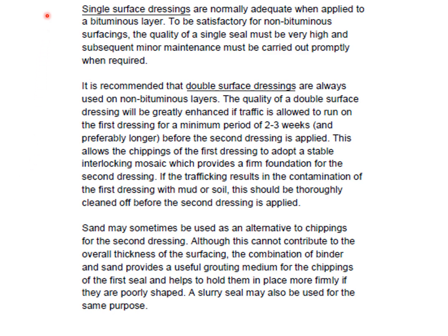Single surface dressings are normally adequate when applied to a bituminous layer. To be satisfactory for non-bituminous surfacing, the quality of a single seal must be very high, and subsequent minor maintenance must be carried out promptly when required. It is recommended that double surface dressings are always used on a non-bituminous layer.